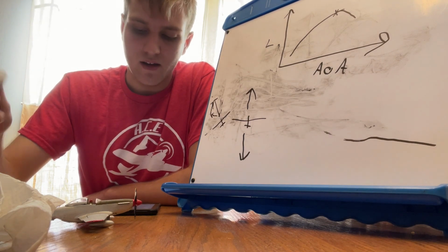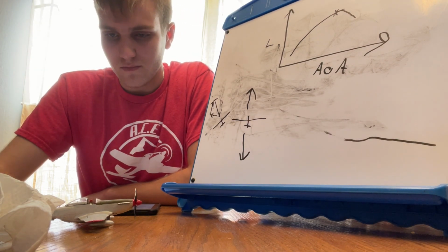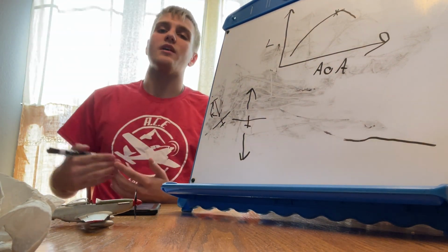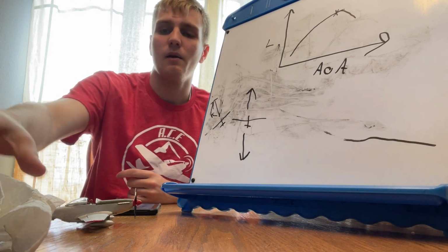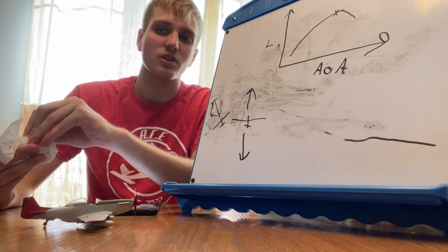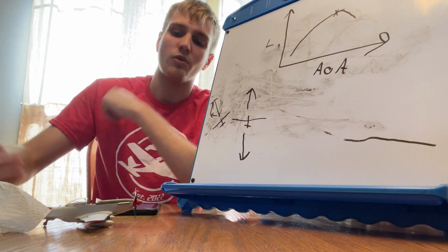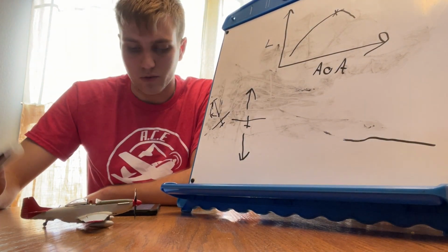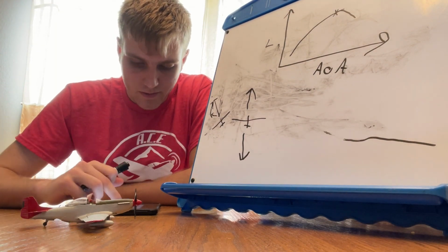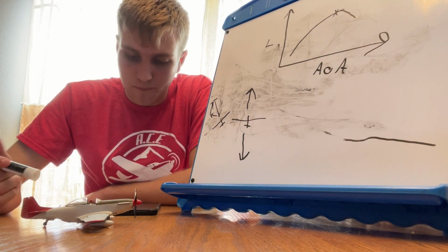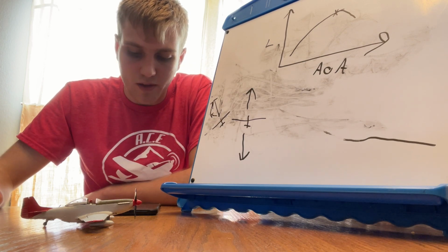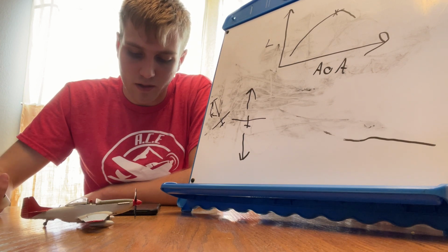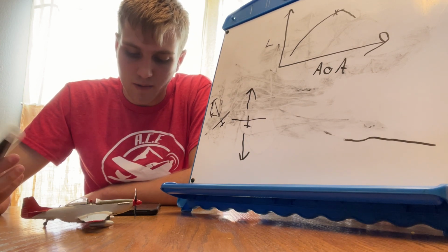I'd let them answer that, then I'll explain to them. It's actually not going to exceed the limit of the airplane because the airplane was designed with that in mind. So that 100 pound weight limit in the baggage compartment is actually rated for 400 pounds, because it takes load factor into account. So that's how load factor works. There are also some things where load factor affects your stall speed and other things, but we will not get into that today.